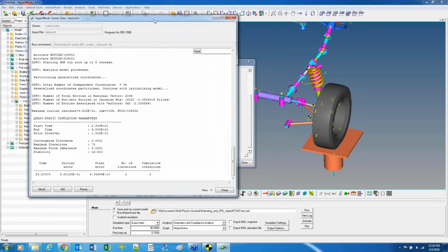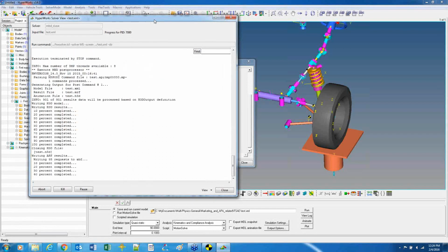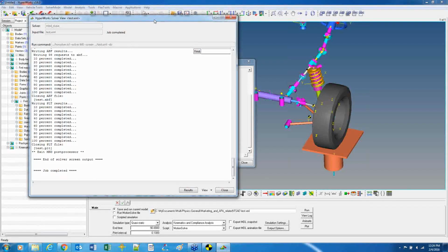So now mathematically it's walking through time, and this model has an input description that says, okay, for 5 seconds I want you to push up and down on the wheels, and for another 5 seconds I want you to laterally push inward, and on and on, and it builds all those different responses based off of the prescribed input. So in this particular case, it's what's called a quasi-static simulation. When you run a multi-body dynamics model, you can run fully dynamic models where masses and inertias and velocities make a big effect, or in cases where it applies, and suspension modeling is really the lead case, you can have the solution be a little simpler by running a static analysis subsequently and having things like the input values be a function of time, and then you just run a sequence of static runs. That's called a quasi-static simulation, and that's what we just did here.